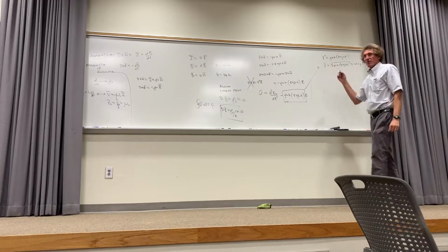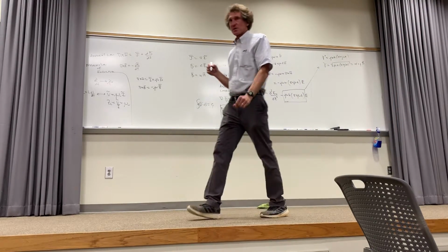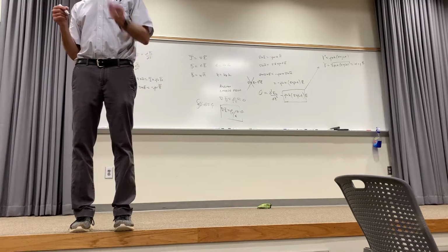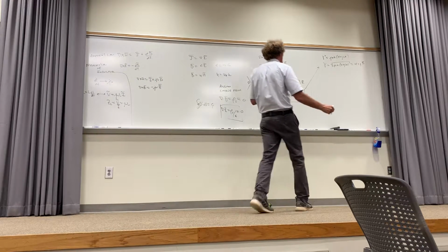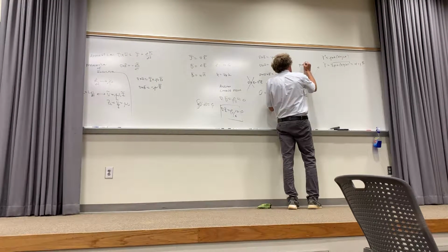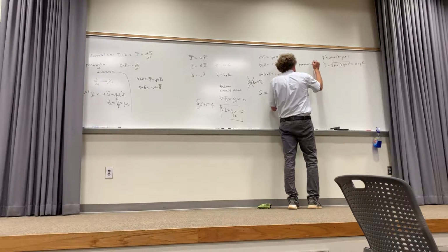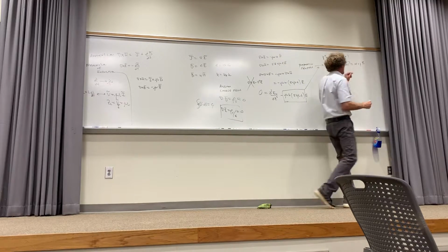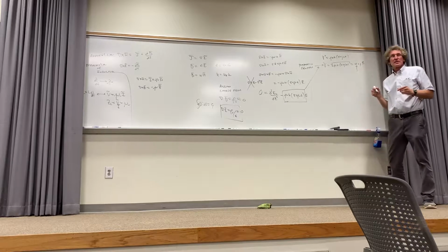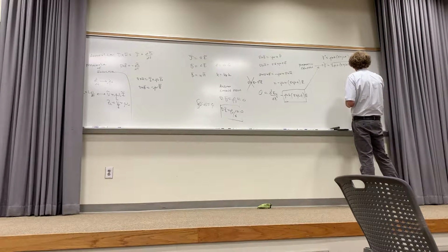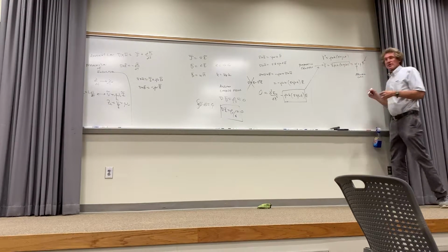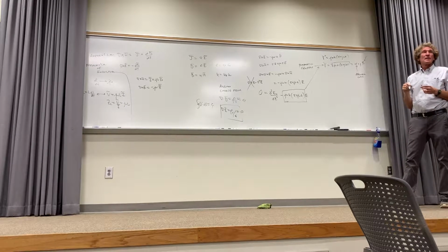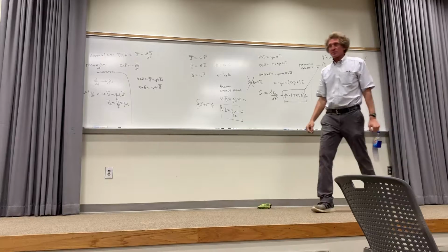Does anybody remember what gamma's called? You had it in your transmission lines. When you did transmission lines, you also had it in chapter 5. Anybody? Propagation. Propagation constant. Right, very good. So this is the propagation constant. Now, it's equal to alpha. Do you remember what alpha is, anyone? Attenuation coefficient. And beta, anyone? Say again? It's phase constant, that's acceptable.